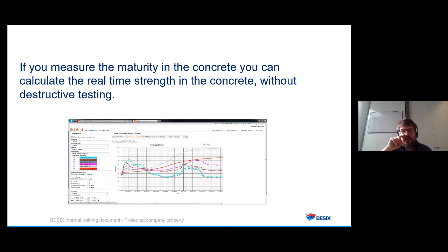Also, you take into account the temperature that is inside your concrete, which is absolutely not the same as the temperature inside small samples that you take into the lab, and then you can crush. This means that you take into account the temperature of the element and the temperature coming out of the hydration process, which is going to accelerate the compressive strength. And this means that you will be able to remove the formwork or do the post-tensioning faster than foreseen.